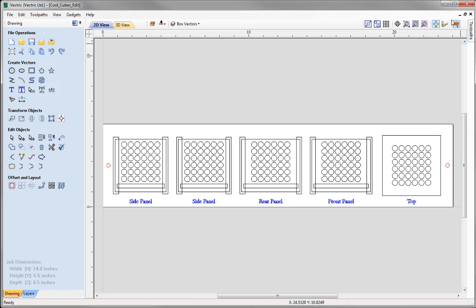You'll notice that the icon has changed. It's got an additional bottom side here, and it's currently highlighted. So I can see that multi-sided view is currently switched on. Another way to access multi-sided view is by pressing the equals key on the keyboard. So if I press equals now, that's going to turn multi-sided view off. If I press equals key again, it's going to switch that on. Now you've probably noticed there hasn't been much of a change here in what we can see in our part, and that's because we don't currently have any data on the bottom side.